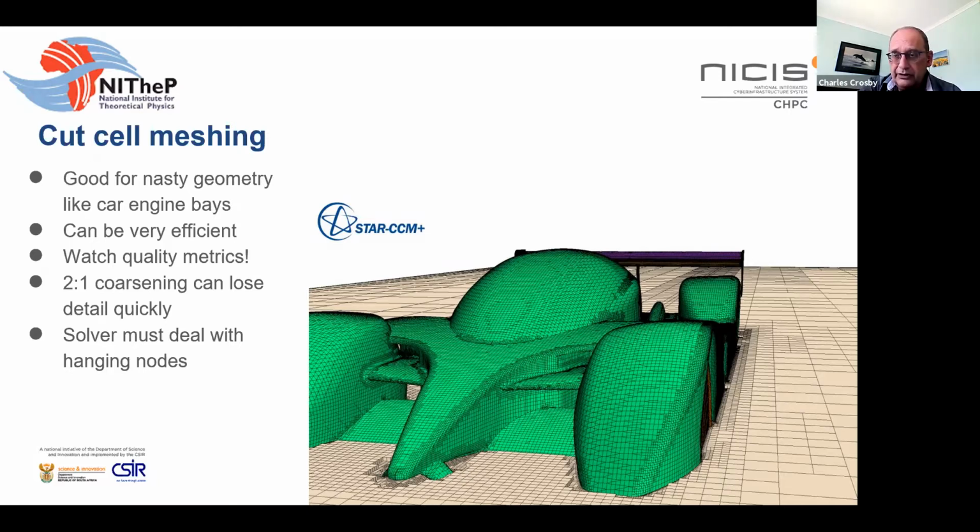And Andrew's comment here, usually want the mesh to be finer where there are large gradients, is extremely important. If you're after good results, it's almost more important to make sure that you've got the grid refined in the regions where things really happen than to worry too much about the overall refinement or cell count. By focusing on the regions that are important, you can get the answers resolved to a high degree of accuracy without needing to fine up the grid in the rest of the region. So that's a really important point, that you can selectively do it.